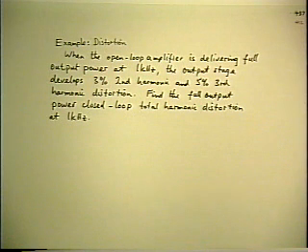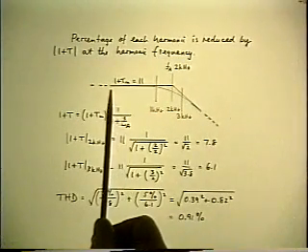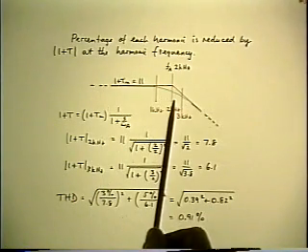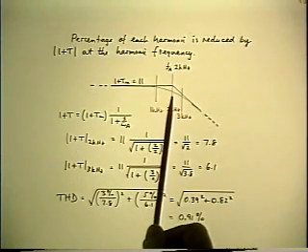So all you have to do is use the result that we set up before, that feedback reduces the distortion to output transfer function by the amount of feedback. And all you have to do is evaluate the amount of feedback at each harmonic frequency. So this is what the feedback factor is. Feedback factor is F, 1 plus T. And we've already gone through the graphical construction and written the factored pole zero form for F. So we have this result already.